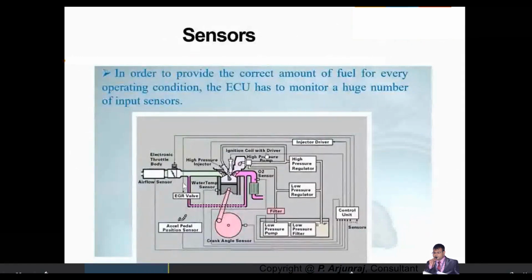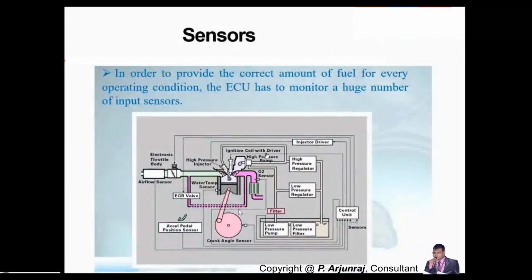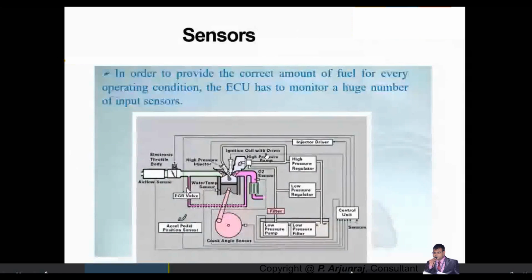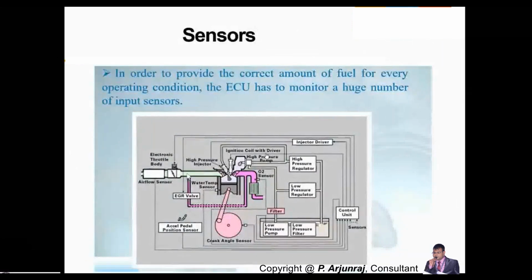And with respect to the system, nowadays you have the EGR valve even for a gasoline engine also, and accordingly the exhaust gas gets recirculated to the intake manifold. And when the exhaust gas is getting recirculated to the intake manifold, what happens? It mixes with the air. The temperature of the air is going to get increased. Okay, and the premix will also happen. The air along with the fuel, the temperature again is going to get slightly higher, and that is going to get injected into the system. So this is the complete loop that you are going to get. Basically, it is a closed loop.